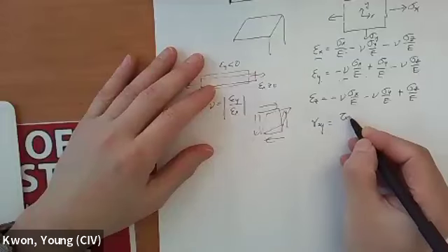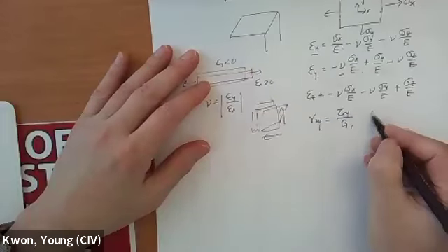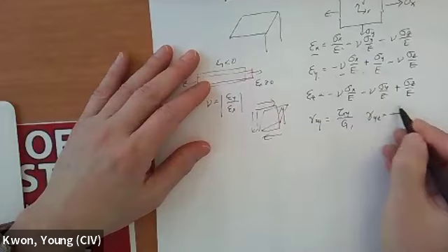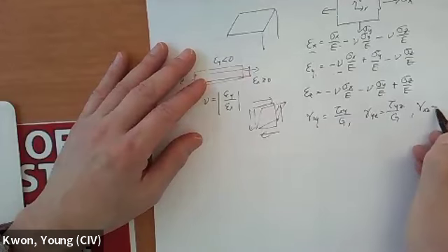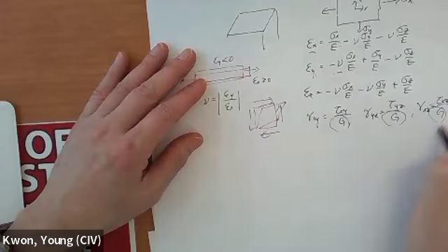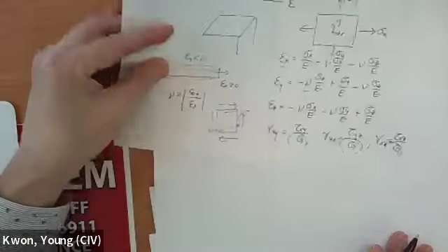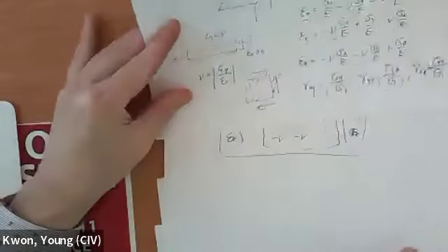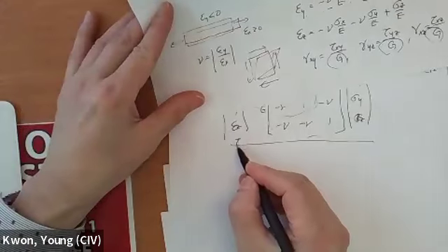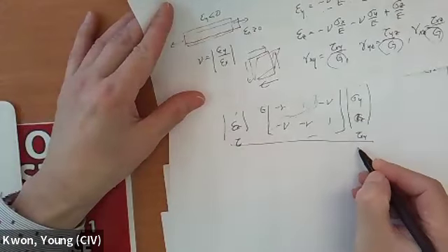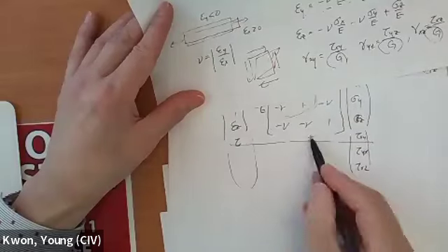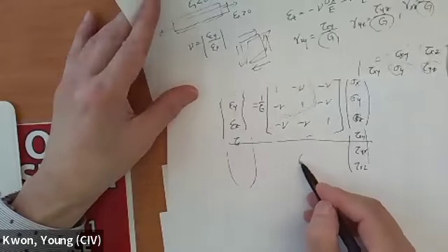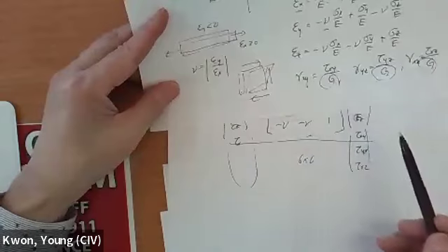So that's going to be tau xy over G. And same thing, gamma yz is going to be tau yz over G, and gamma xz is going to be tau xz over G, for isotropic material and shear modulus, right? So eventually you can write, if you include tau xy and tau yx and tau xz, so 6 by 6, then that's going to be extended from 3 by 3 to 6 by 6, okay? But those are going to be diagonal matrix.